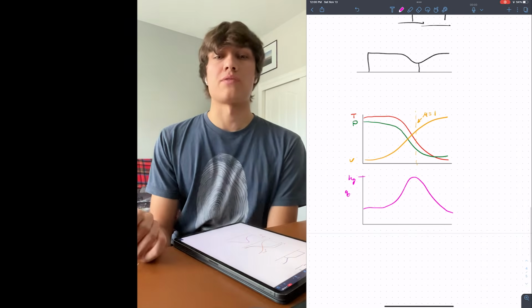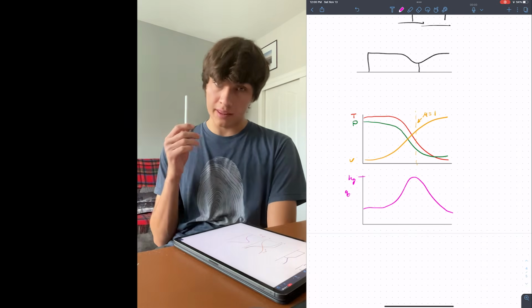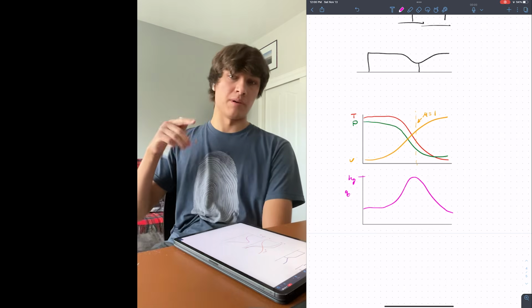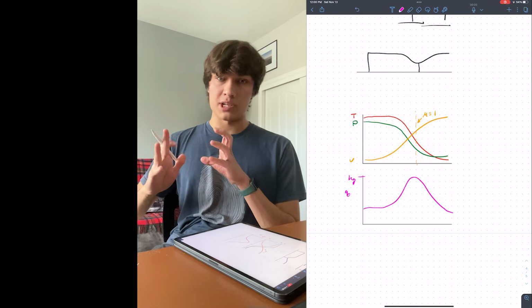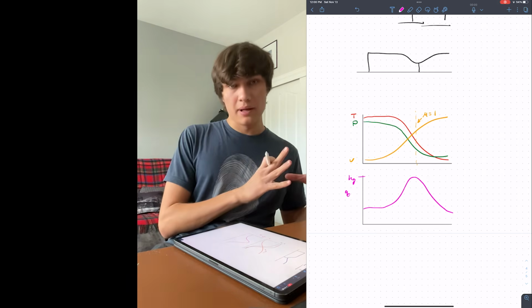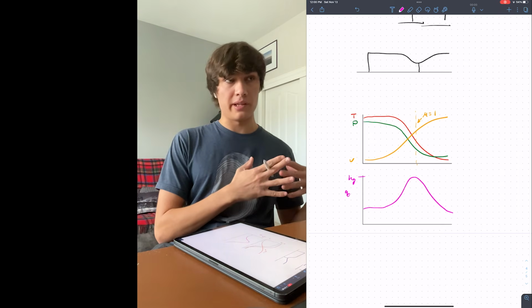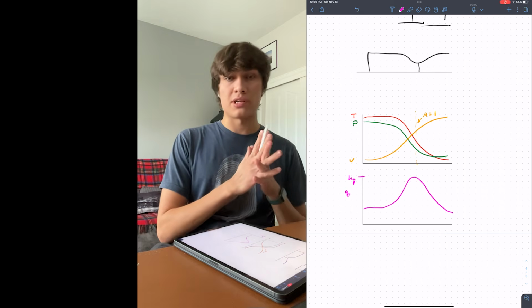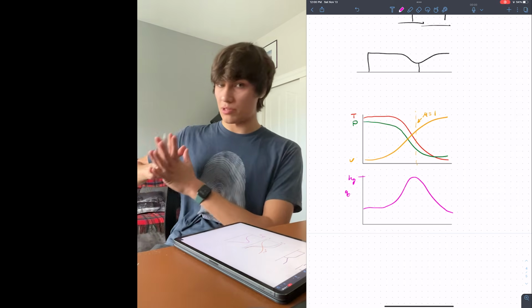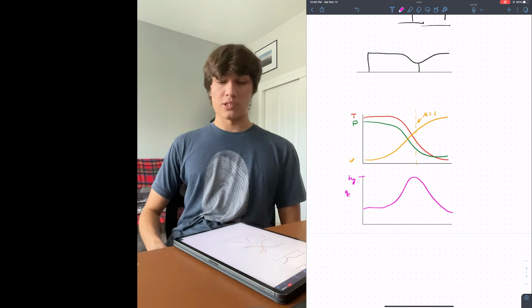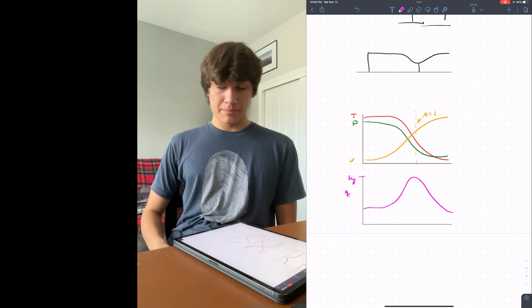One final note about the heat transfer is that there's a lot of this big asterisk above this, but in general, the radiative heat transfer regime matters a lot in the chamber and doesn't matter as much in the nozzle. The primary effect for this is that the chamber temperature can be like 3000 Kelvin, where there's a lot of radiative heat transfer, while in the nozzle it drops off significantly, and also so does the density. So keep that in mind.